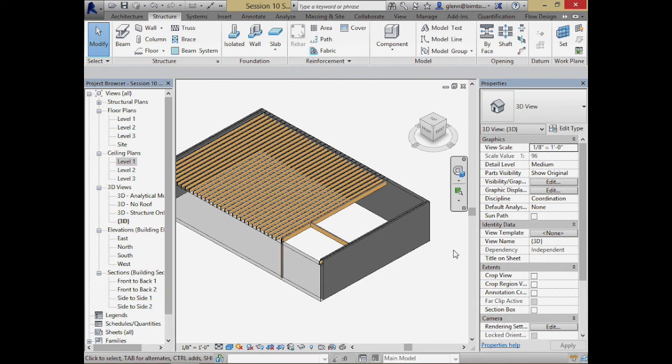Although there was some really interesting research a couple of years ago that Engineers for a Sustainable World were doing with Peruvian schools, where they were reinforcing Adobe, because they have a lot of schoolhouses in an earthquake-prone area, and unreinforced tends to shatter. That's really catastrophic. So there are ways of reinforcing older ones to add a little strength to resist that. It's great for gravity loads, it's just the lateral that's the issue.